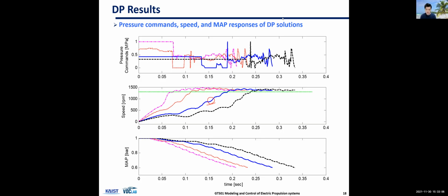And you're looking at manifold pressure. Because the engine rotates faster, manifold pressure drops faster. Okay. And you can also see that you can start the engine faster because you apply higher clutch pressure, and as you lower clutch pressure, you start the engine slower. Okay.